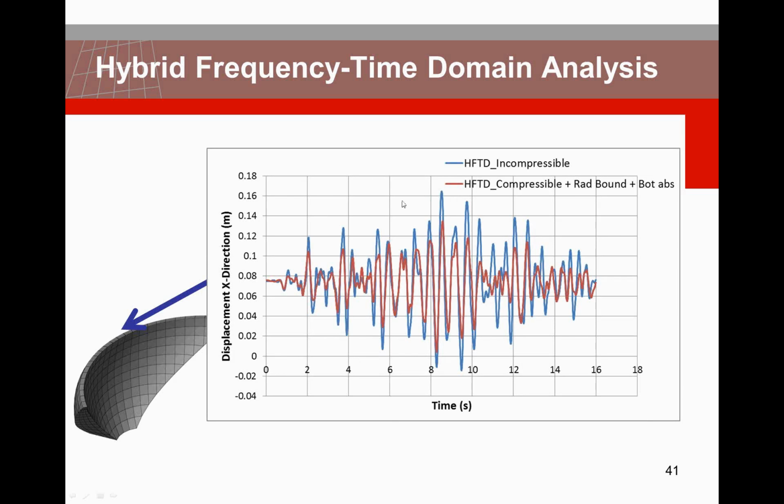What you can also see here, if you just calculate, say, a dam, so that we take the displacement here at the top of the dam, and you do just an incompressible calculation, then you will see exactly the same time history as if you would have done a nonlinear transient dynamic analysis. But if you want to take into account compressibility and bottom absorption and radiation boundaries, you see that you have more energy dissipation and your peaks, your maximum displacement, will be much lower.